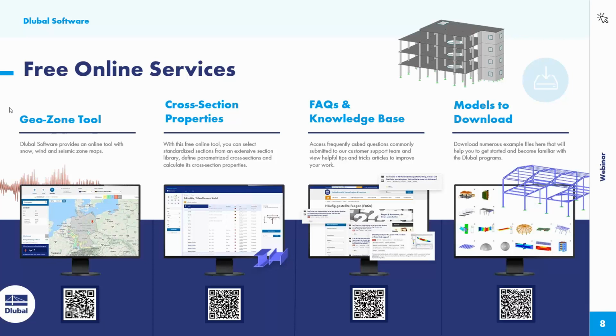And then there was a second question, instead of angle, can we use a vector to orient the beams? Yes, that's what I also showed briefly at least. You can orient them based on nodes, for example. Is it possible to generate the 3D wind on the elements, wind tunnel, according to real code in Grasshopper for a range of wind zones? No. Just basic loads, nodal, line, member, surface loads. Anything more advanced like the wind tunnel and so on, this needs to be done in RFEM 6 with the add-ons there. Yeah, that's, I think, all the open questions.